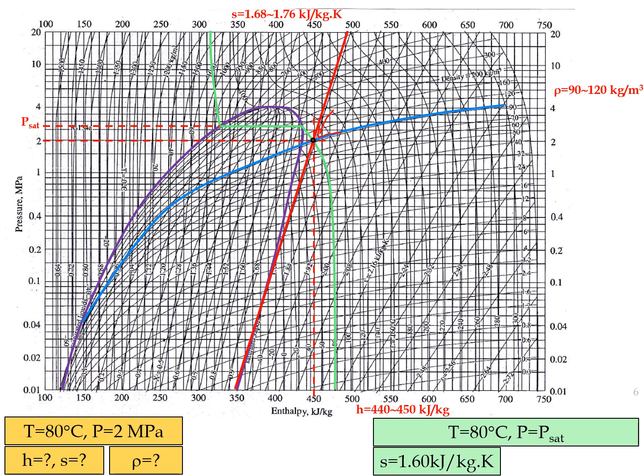So here we need another piece of information, and in this case it is given the entropy value, which is around 1.60. From there we can draw a straight line from the entropy line, and we know the crossing point here, and from there we can know the value of H, rho, and also the value of X. The value of X here is the ratio of the vapor to the liquid phase, so it is around 0.6 to 0.7.